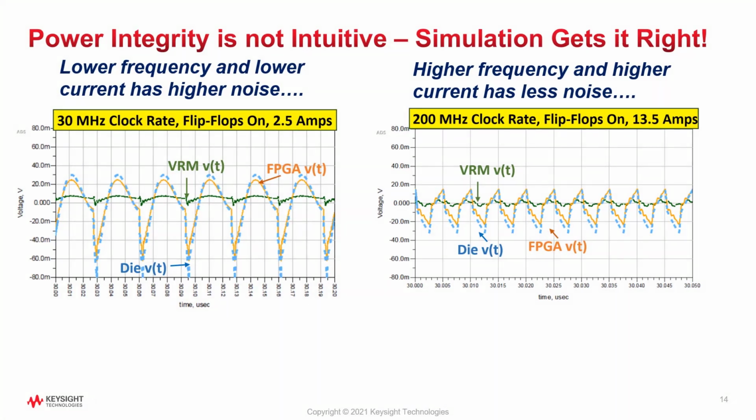The three-step power integrity workflow identified a resonant impedance peak at 30 MHz, which should correspond to excessive power rail ripple if the dynamic load switches at this frequency. Intuition usually tells us that higher current and faster switching frequencies should cause more voltage noise ripple, but this was not the case when increasing the dynamic load from 30 MHz to 200 MHz on the ZCU-104 board.